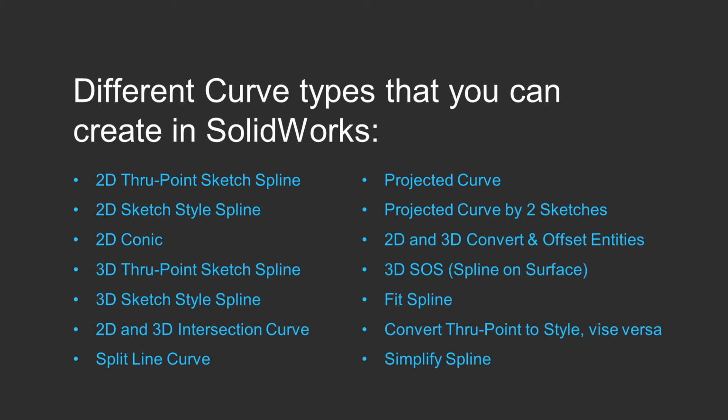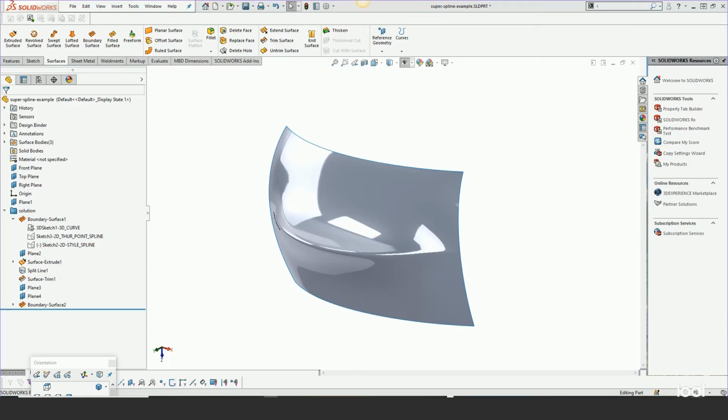And then you have the ability to take, for instance, imported curves or convert edge curves or offset curves and simplify them, meaning you can modify them to simplify their degrees, free them up, delete constraints, and it's a way of taking existing curve geometry and further manipulating it. So with that, let's get into our example model.